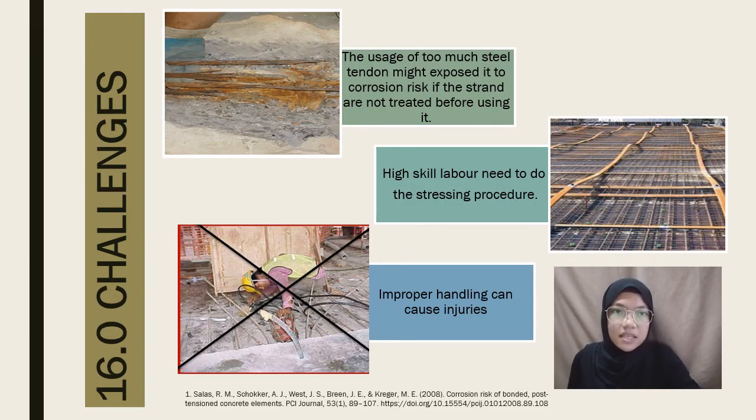The challenges that were faced by the contractors during the construction of this post-tension slab: they are exposed to the corrosion threat. The usage of too much steel tendon might expose it to the corrosion risk if the strands are not treated before using them. The second challenge that was faced by the contractor is that high-skilled labor is needed to do the stressing procedure.